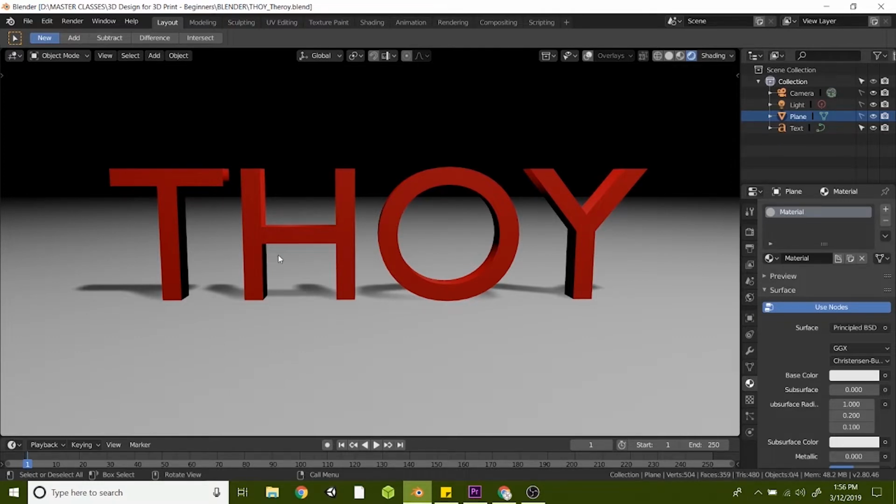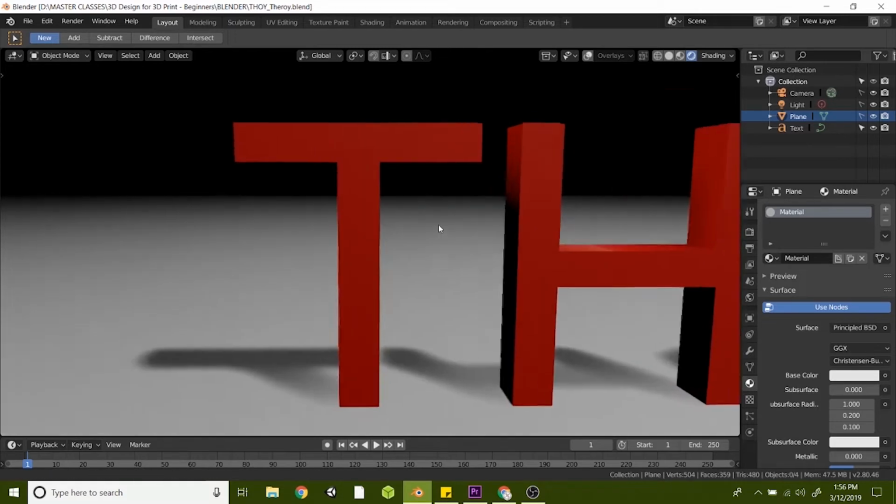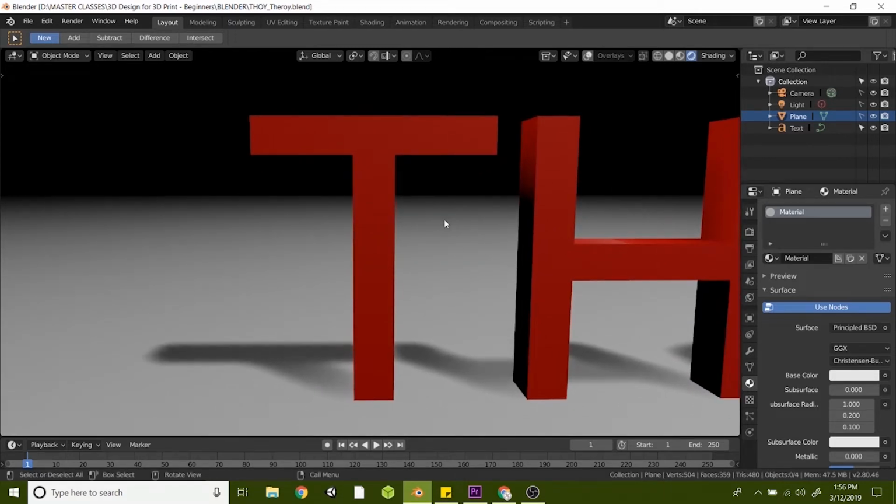First we have the T, which represents overhangs, like the T here, just kind of 90 degrees over here to floating. What's going to happen is when the 3D printer goes to print this, when it goes out here, it's going to start drooping. So the only way to combat this is to add support material in an external 3D slicing software of your choice. I'm not saying that you can't design something with overhangs like this, but just keep in mind if you're going to have something that is tall and has overhanging edges, then they may need support material.